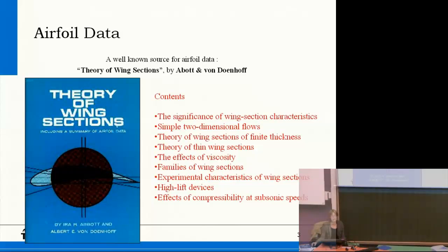And the first thing they do is for infinite wings. They call it infinite wings. What you do then in the wind tunnel, you pretend that the wing is infinitely long, so you have sort of end plates, and ideally as long as possible wing with the same airfoil, and then you can test all the airfoil characteristics. Of course, the realistic wing consists of different sections with different airfoils and is finite. So afterwards, once you have understood sort of the properties of the airfoils, you look at then the sort of sections and you look at the finiteness of the wing. So that's also how we will build now chapter 5 up.